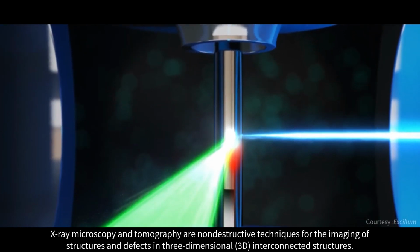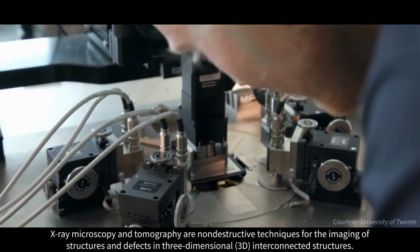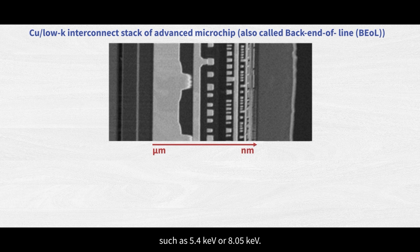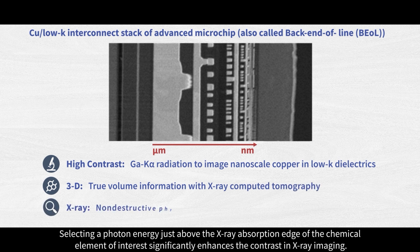X-ray microscopy and tomography are non-destructive techniques for the imaging of structures and defects in three-dimensional interconnected structures. However, the image contrast is often weak with commonly used photon energies, such as 5.4 keV or 8.05 keV. Selecting a photon energy just above the X-ray absorption edge of the chemical element of interest significantly enhances the contrast